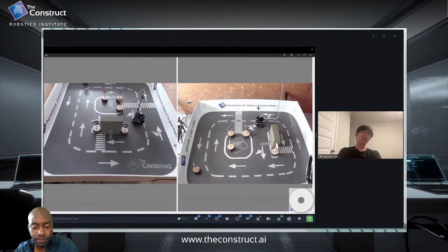Also, if you want to be closer to the obstacle, you can decrease the threshold. Did you play around with it at some point to reduce it? I maybe played around with it. Sometimes it just ran into the wall, so I thought, let's try to be safe, even though it might turn multiple times. As long as it doesn't hit the obstacles, it's doing its thing. So I pretty much set it back to the default. I thought there's a reason why you guys set the threshold as 0.3. So I just went back to the normal threshold.